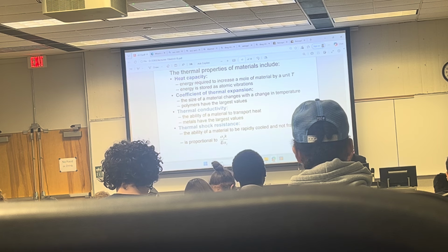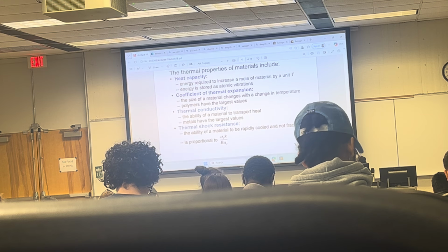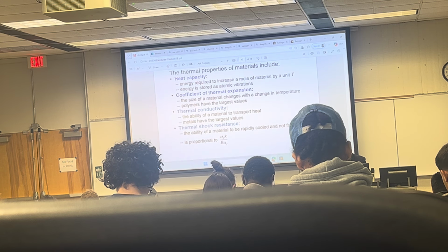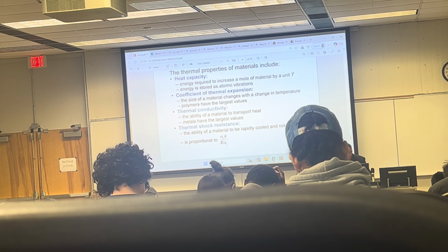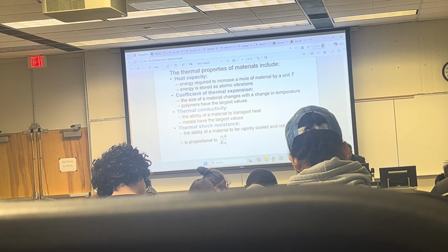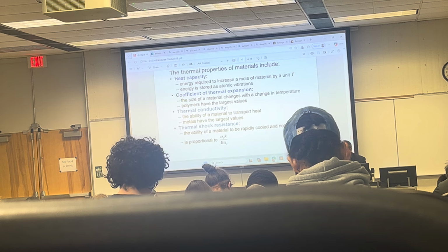There's solidification of a material, and so it goes from liquid to a solid. And this nucleation is homogeneous. And you're given latent heat of fusion and surface free energy. And you're given the melting temperature. The first part is asking to calculate the critical radius for the supercooling of a certain number of degrees.